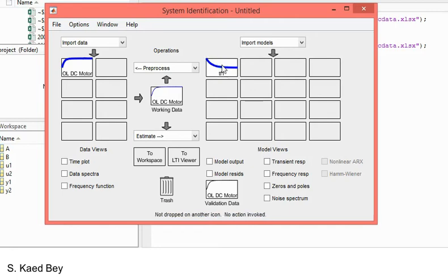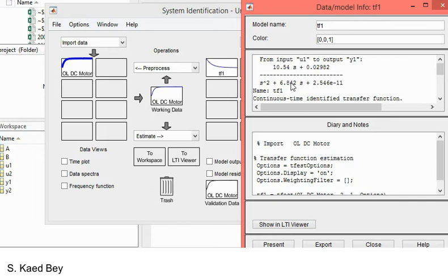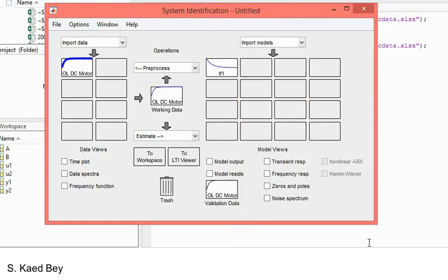If you just click on it, this is your transfer function. You can use this transfer function to represent your motor driver and the motor itself. You could take that model into Matlab. You can analyze open loop, closed loop, find your PID parameters, same as we've done in our previous videos. That's it for what I need to achieve in this video.